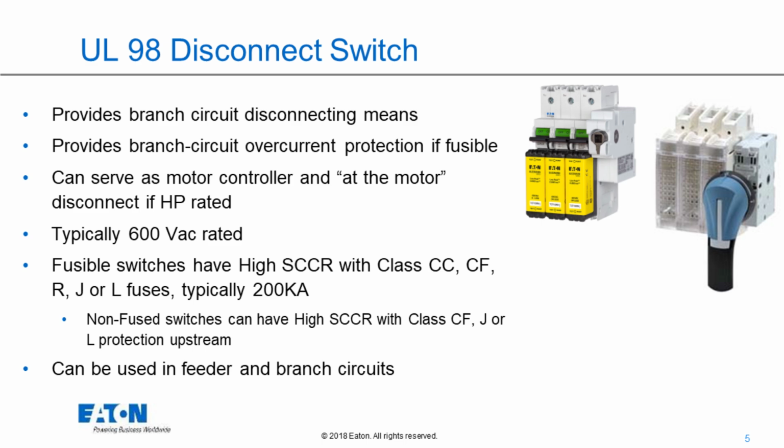The Compact Circuit Protector takes up 45% less surface area on the back plane of a control panel. If you compare the height times the width, well, these are 200 amp switches, so some of the other amperages can go up to like 69% less, but comparing these 200s, it's 45% less surface area on the back plane of a control panel.